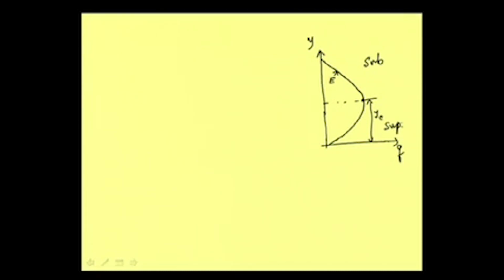With the change of unit discharge, depth is changing, that is of course obvious, but if the flow is in the subcritical zone, then with the increase of unit discharge, you can see that the curve shows depth is decreasing. When your Q is increasing in this direction, depth is decreasing.